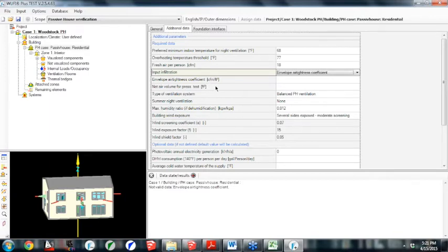I'm going to choose this envelope airtight coefficient because that is how the new standard is set up. We are testing for 0.05 CFM per square foot of envelope or less. So this changes quite a bit for smaller projects. It allows you to go quite a bit above the 0.6 air changes per hour, but for the larger projects, it shrinks that allowance for you. It can get down to 0.3 for some of the larger projects I've seen. So it kind of levels the playing field.